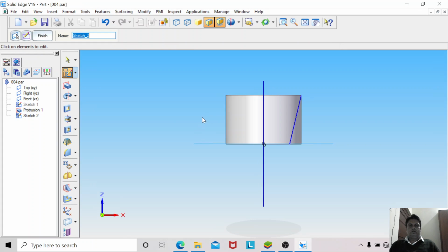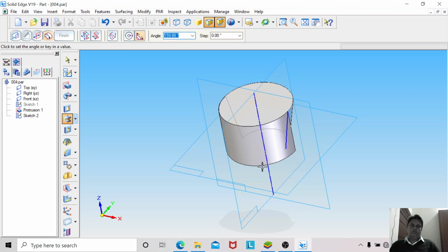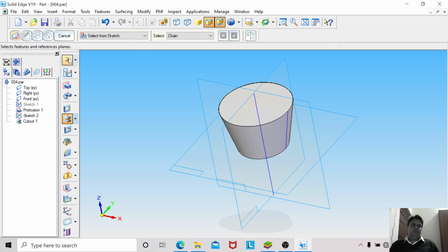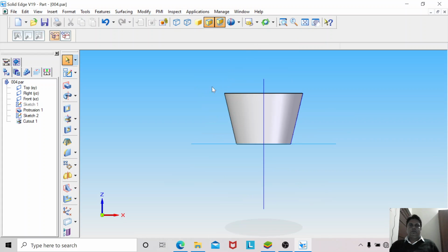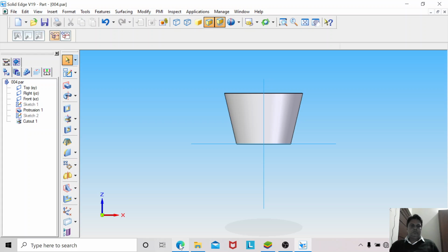Return to the 3D environment and revolve it using revolved cutout. Select this section, enter, select the axis, and it will ask the direction in which the material is removed. You give that the outside of this material should be removed. Click on it, revolve it, give 360 degrees and right click. Now the material has been removed. Immediately hide the sketch, and now look at the drawing.